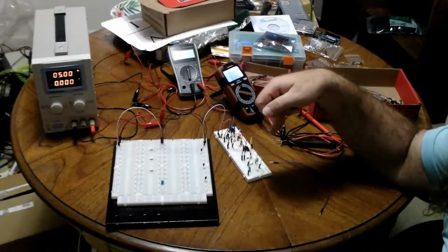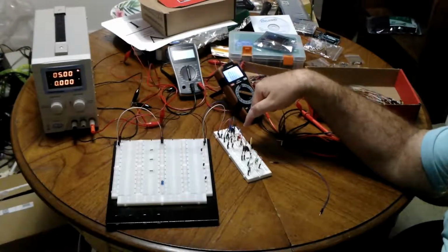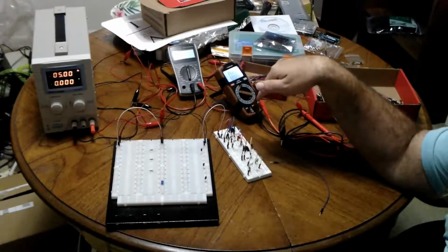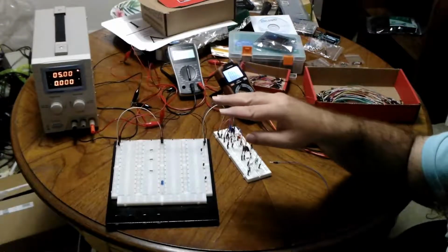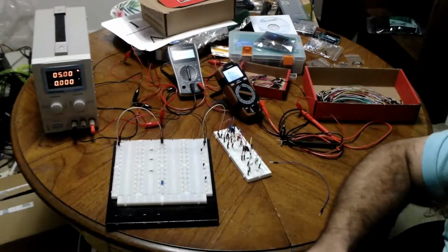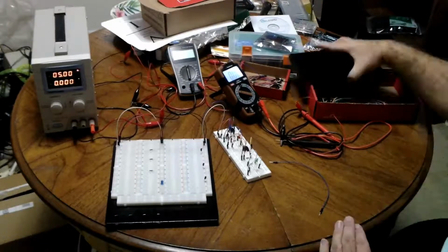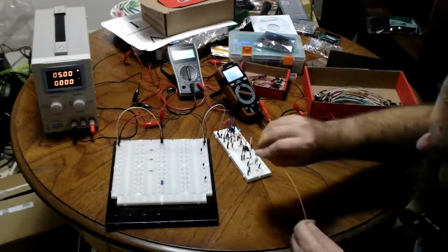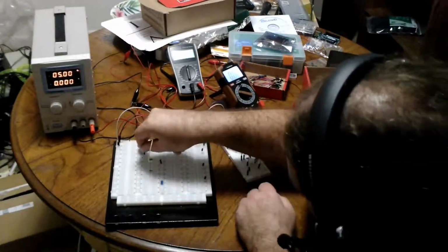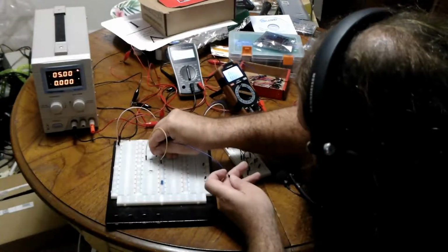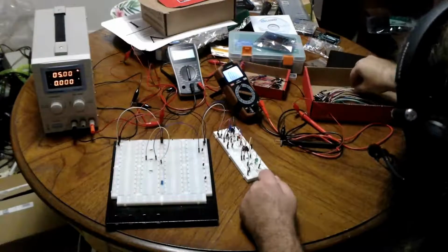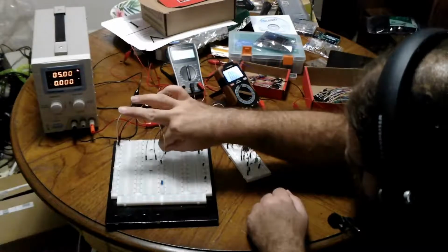So as I said, make sure your inputs are well behaved. We've got resistors going through here, so wherever we use these inputs, we don't have to worry about it. They're well behaved. So all we need is resistors through the transistors. So the NOT gate is very simple. We have positive power into a resistor. That resistor goes into the transistor. The transistor goes back to negative power.